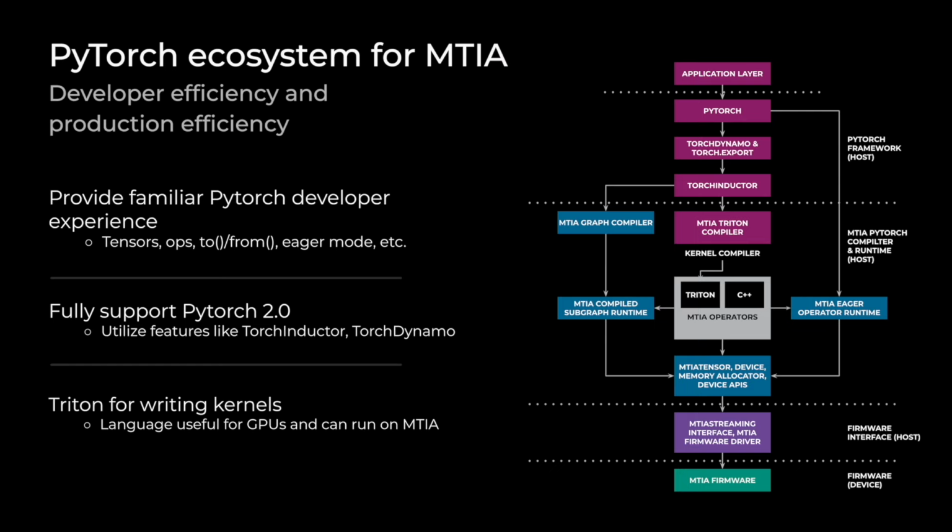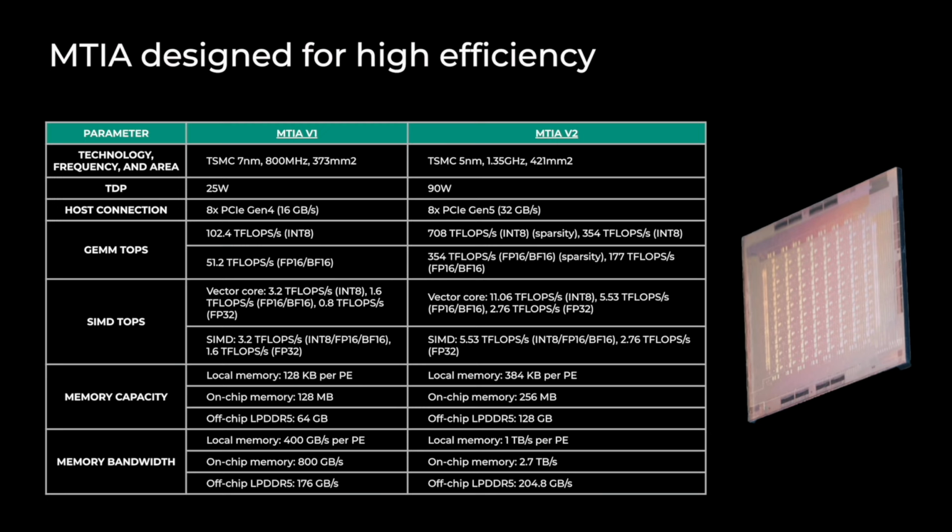So finally, I'd like to share a comparison between MTIA v1 and MTIA v2. Compared to the chip we announced last year, our v2 design is much more powerful. And this was one of our main goals. We wanted to be able to have it be more capable to serve even larger models to improve our applications. So a few things I'd highlight. We have 2x more on-chip SRAM, which improves our performance. We doubled the LPDDR off-chip to serve larger models. We've increased the on-chip SRAM bandwidth by 3x, and we've done that really to feed 3x more peak flops, which allows us to serve those more complex models.